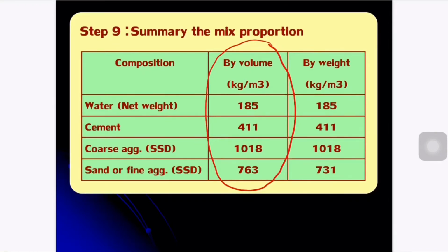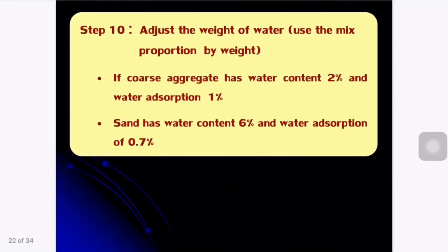After we have the concrete mix proportion as shown in the table, it is noted that both coarse and fine aggregates are in SSD condition. Actually, coarse and fine aggregates used in construction sites are not in SSD condition, may be dry or wet, depending on the weather of the mixing day. We cannot control the slump or quality of the concrete. Thus, we have to adjust the water in the concrete mix proportion due to the moisture content in aggregates.